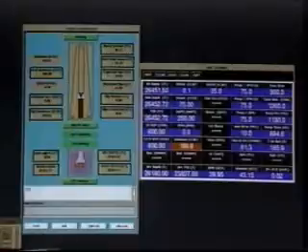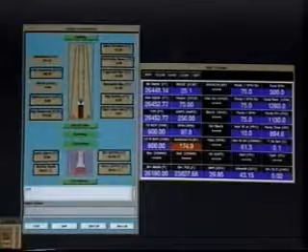But remember that there's a lot more to planning a well profile than drawing a curve from point A to point B. Many other factors, well spacing, casing and completion requirements, rig capacity, hydraulics, drill string design and specifications, drilling parameters, and so forth, come into play. There are a number of software packages that can be used to optimize well trajectories while accounting for these drilling variables. Of course, it's one thing to plan a well profile and another to actually attain it.